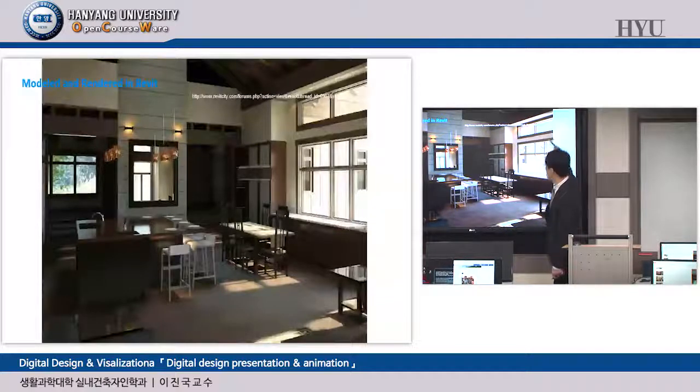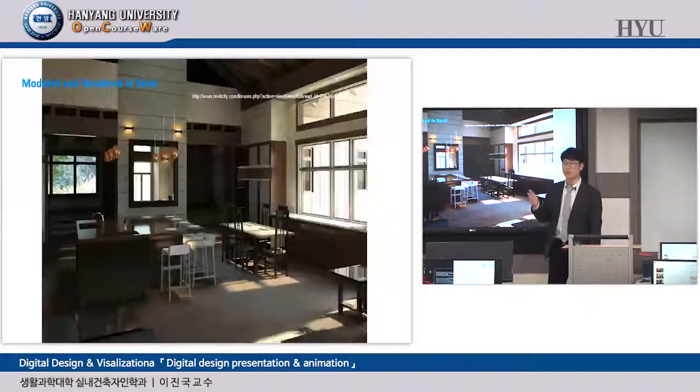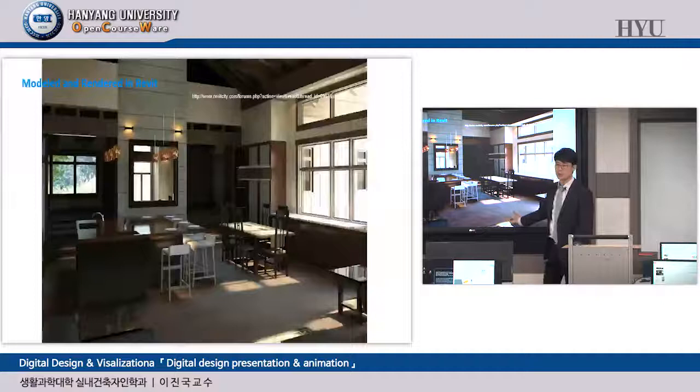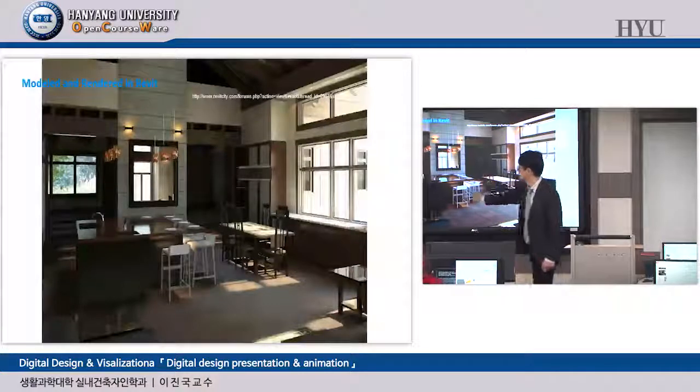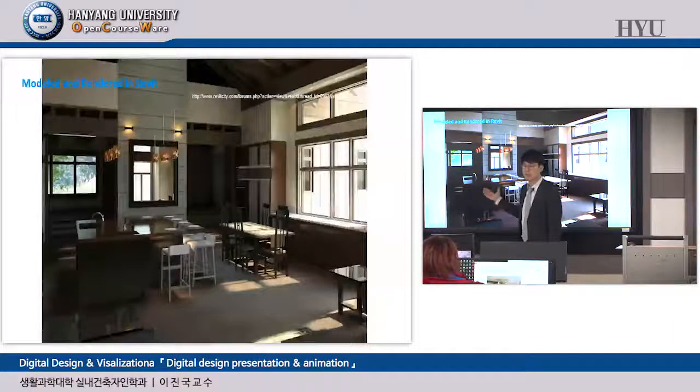I told you, Revit knows the sun's height and the location, simply because this building has an address. The meaning of this one having an address is simply that this one has a precise location in altitude, longitude on this planet. That is, we can precisely calculate sunshade, okay, daytime. And all these components are Revit parts, Revit components, Revit families.